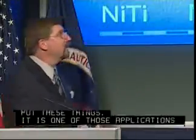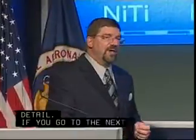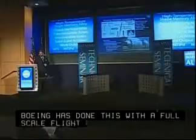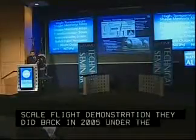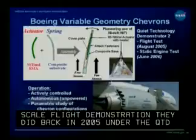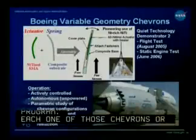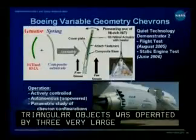So if you go to the next slide, as I said, Boeing has done this with actually a full-scale flight demonstration that they did back in 2005 under their QTD program. Each one of those chevrons, or those triangular objects, was basically operated by 3 very large plate-shaped SMA actuators. And they ran it in various configurations.